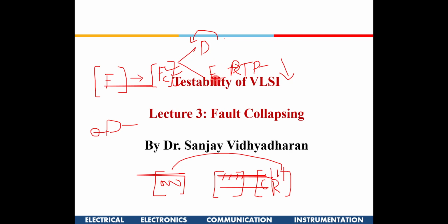Once that is done, a few will be remaining, and for those few, if you start doing random test patterns, it will take a lot of time, and you may not come across those faults at all. So what we do is we take those limited number of faults, and each one of them we handle as a single fault and try to find the test vector to detect that fault. So overall, that is how to go about designing a test bench. Some rough idea you have got?